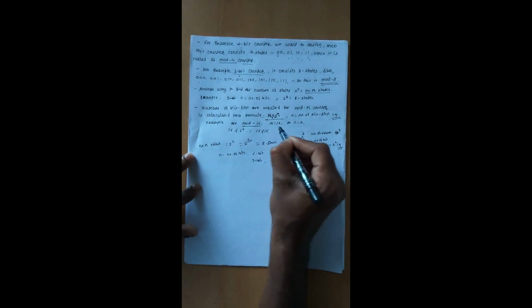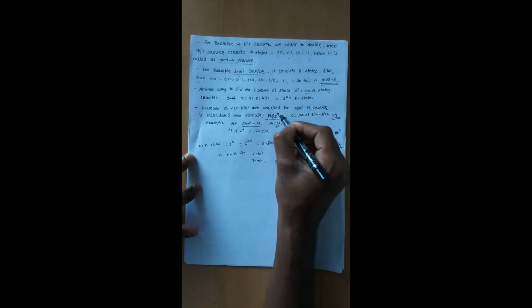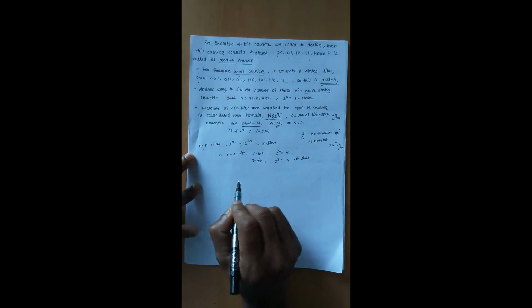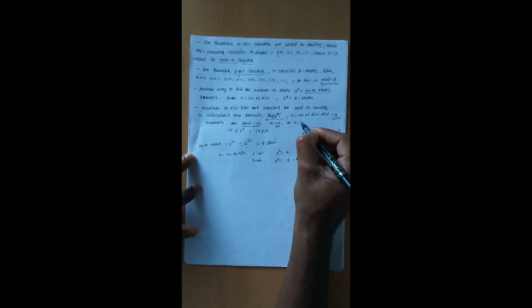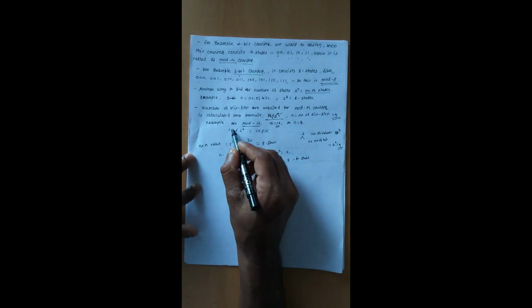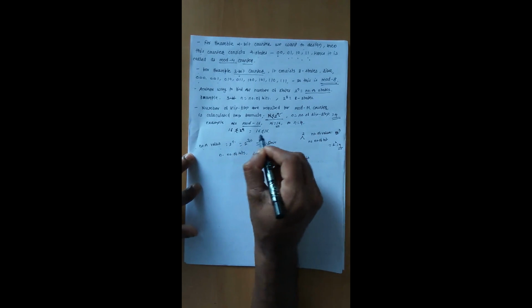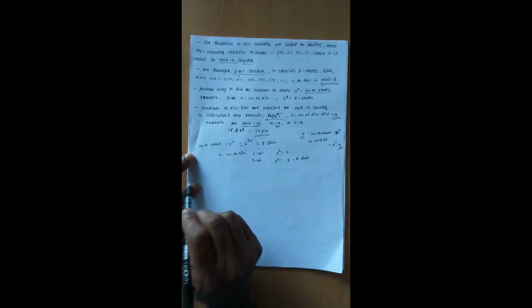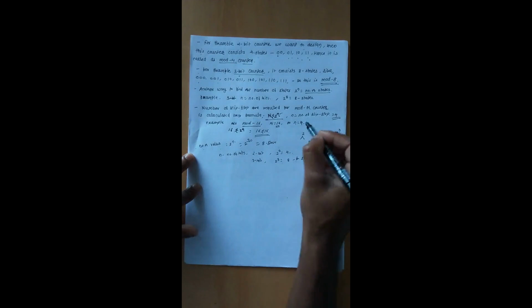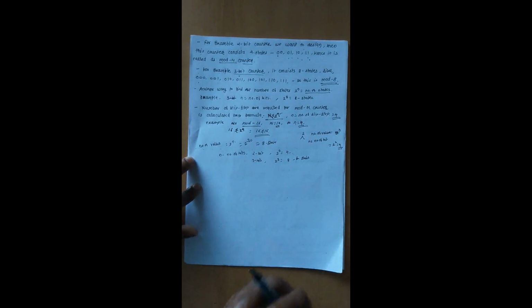So here N is equal to 16, and at which value of n will this equation be satisfied? We will consider n is equal to 4. So 16 is less than or equal to 2 raised to 4. So the number of flip-flops required is 4. In this way we can find it for any value.